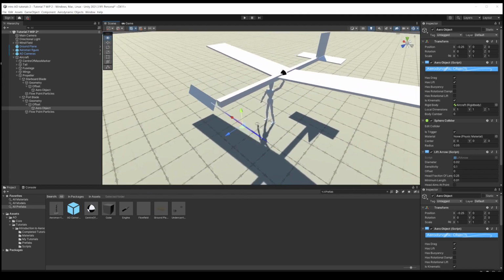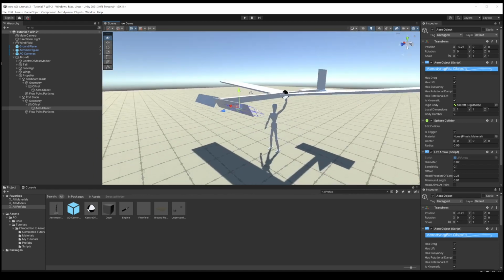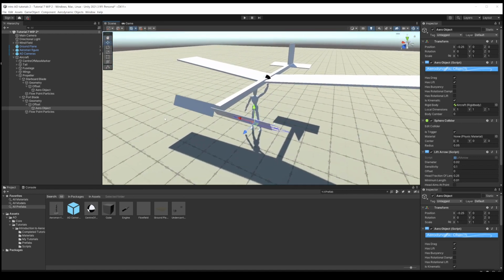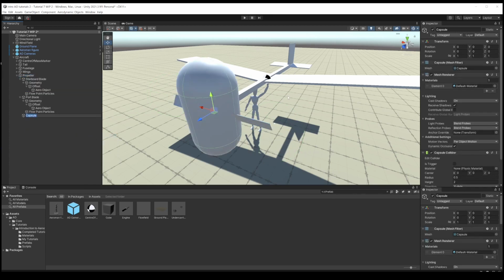Okay, I'm liking that, but it doesn't look very aerodynamic at the front, and just because we want to make it look slightly nicer, let's put a little nose on the front, a spinner on the propeller. So if we go up to propeller, 3D objects, and then we want a capsule. Drops in a standard capsule. Let's click equal scaling and 0.2 size, and then let's just rotate it round.